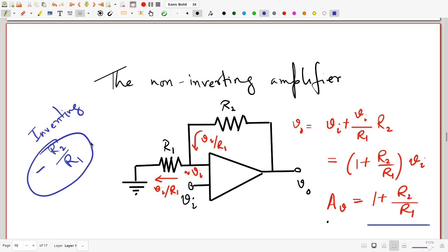So if you want a positive gain, you can couple two inverting amplifiers together. Whereas you will never be able to couple non-inverting amplifiers together to get a negative gain. So that way also, purely from the point of view of getting different mathematical formulae in place using circuits, the inverting amplifier should be preferred.